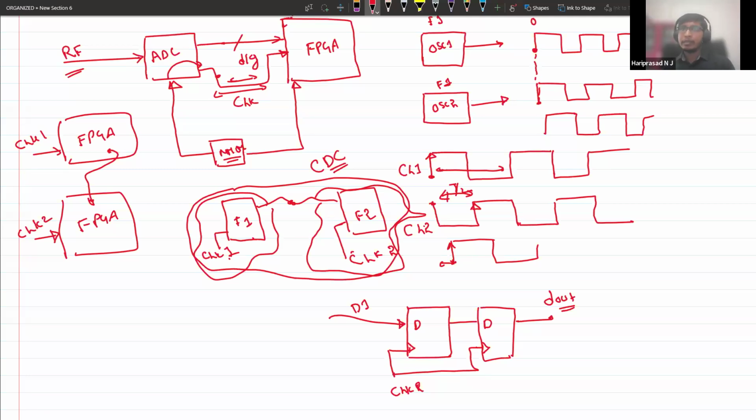This is based on the metastability issue, I mean MTBF analysis. Even here, you cannot assure that it is highly reliable. You can say it is 99% reliable. As you want to increase reliability, you can go for triple flop, four flop, multi-flop synchronization. Ideally, there is a higher probability of data getting corrupted at the first flop, but as you pass through another flip-flop, it will be somewhat stable. So usually we call it double flop. Any questions so far?